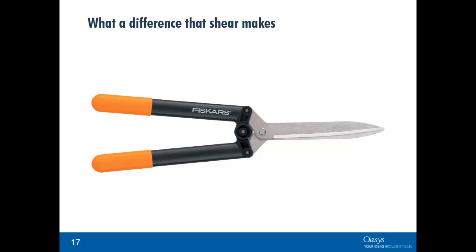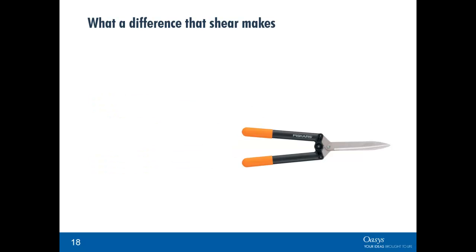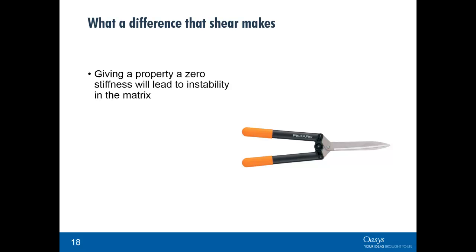And properties as well. I mentioned zeros. You need to avoid zeros in properties. For example, if you want to avoid bending moments in a beam, don't put the bending stiffness to 0. Use a bar instead.